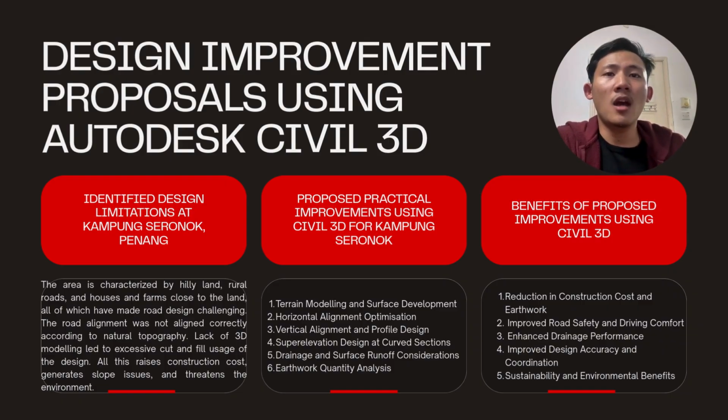In addition, drainage analysis was carried out to identify runoff paths and low points along the road. This helped in proposing suitable side drains and cross drainage locations to prevent water ponding and pavement damage. Civil 3D was also used to calculate cut and fill volume dynamically, allowing better cost estimation and construction planning.